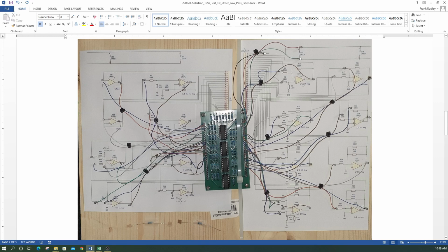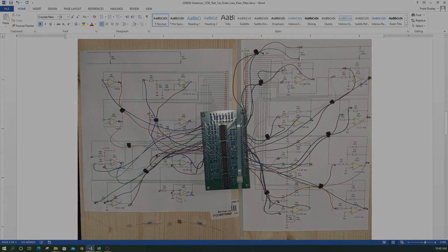because the low on the oscilloscope is a ground. It's not a true low, so it's tied to the house ground. So a lot of times you need a differential amp for your oscilloscope. So this comes in handy for that. Or if I need to reduce the gain or increase impedance, if the input impedance is not high enough, I use one of these followers. But I'm just using this one op amp here to make it into a low pass filter.